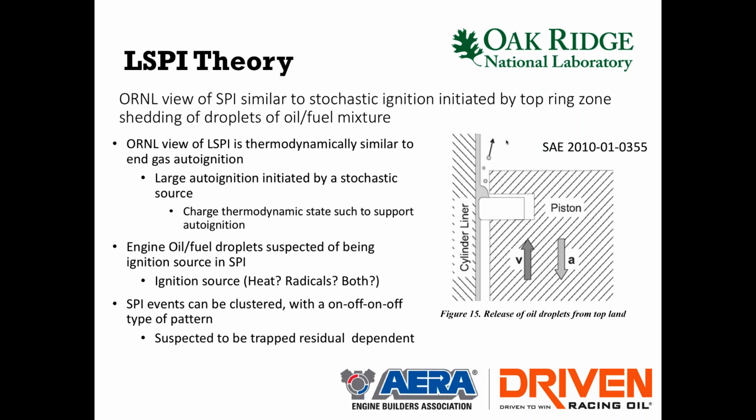When you think about high back pressure on a downsized engine, the higher the amount of back pressure, the less scavenging efficiency you have with the engine, and that lower efficiency leads to more trapped residual. That's what charges the system.